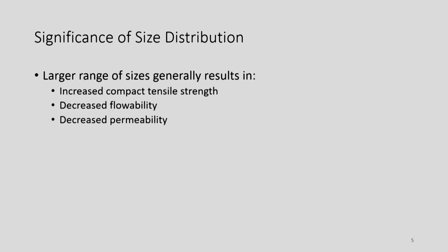Say you are compacting 2 different powders, one with the same size particles and one with a wider distribution. As I mentioned, a wider distribution increases the compact strength, right? So how does a wider distribution increase the strength? Different particles will fit each other. Okay, exactly. So do you know what happens when you compact powders? The mechanism of compaction.